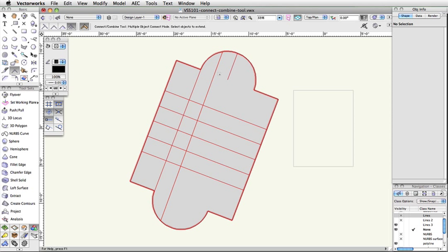Continue to click on objects to connect to the boundary. Each consecutively clicked object will be connected to the boundary until the tool is changed or a blank area is selected. This mode makes it easy to quickly change multiple objects in your drawing without having to adjust values or settings for each individual object.